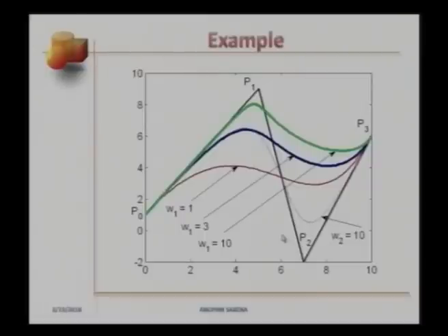The point that I'm trying to make here is, had we considered only a Bézier segment and not the rational Bézier segment, with the same control polyline, I could not have changed the shape of the red curve, which is our original cubic Bézier segment. With the addition of these weights, keeping the control polyline the same, I can now play with the shape of a Bézier segment by merely changing these numbers on the weights. As I increase the weight corresponding to any data point, the curve will gravitate towards that data point.